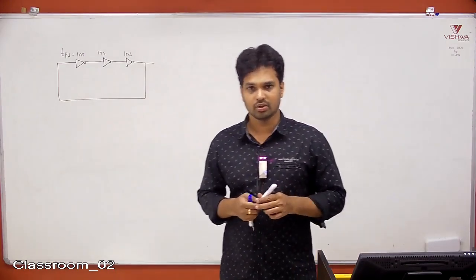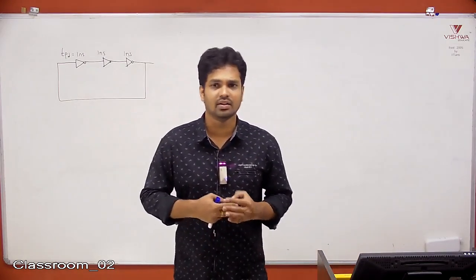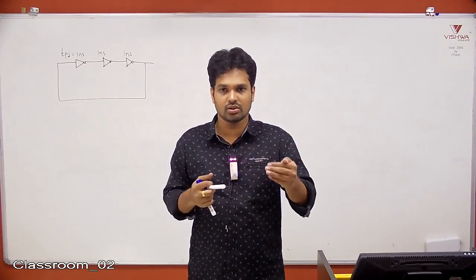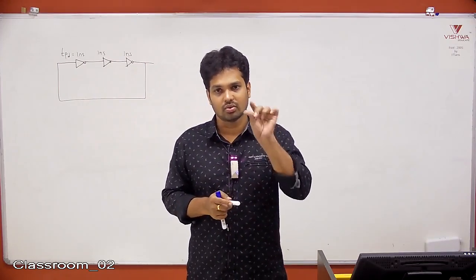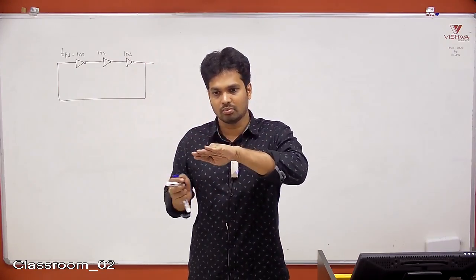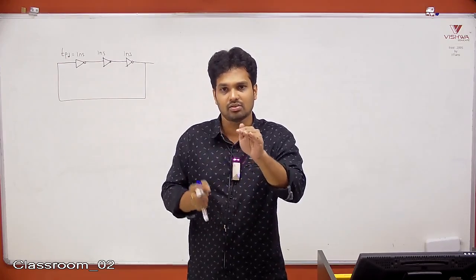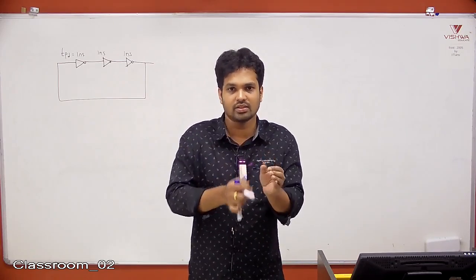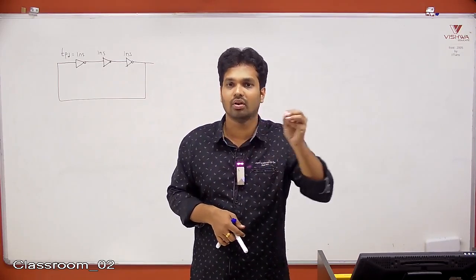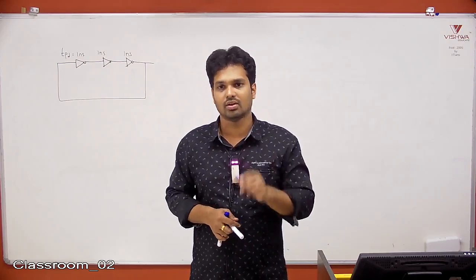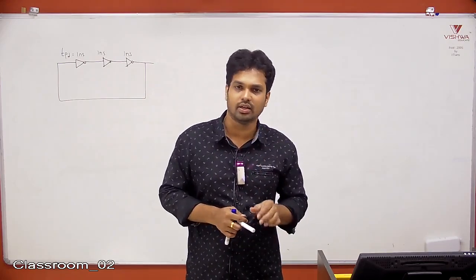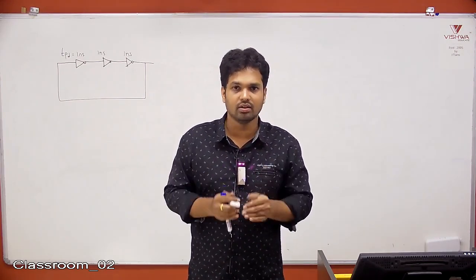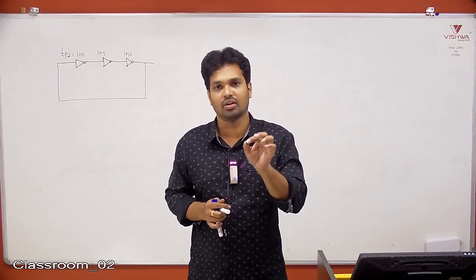When you apply the input in any logic gate, internally your transistors will be changing from on to off condition or off to on, saturation to cutoff or cutoff to saturation. Once you give the input, there will be some capacitance to charge, or load on the input. Because of all these conditions, it requires some time to get your valid output. That is called as propagation delay of the gate. What is propagation delay of that gate? It is the time required to get valid output after applying the input.